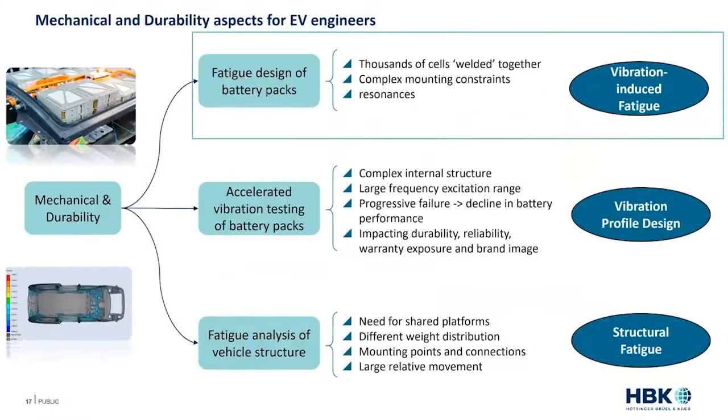Now we have this test spec. Say it's a PSD. We could use it on our shaker to drive our shaker test, but we could also use it in an FEA environment as a loading, as an input for our frequency domain vibration fatigue analysis. So let's take a look at this one now.